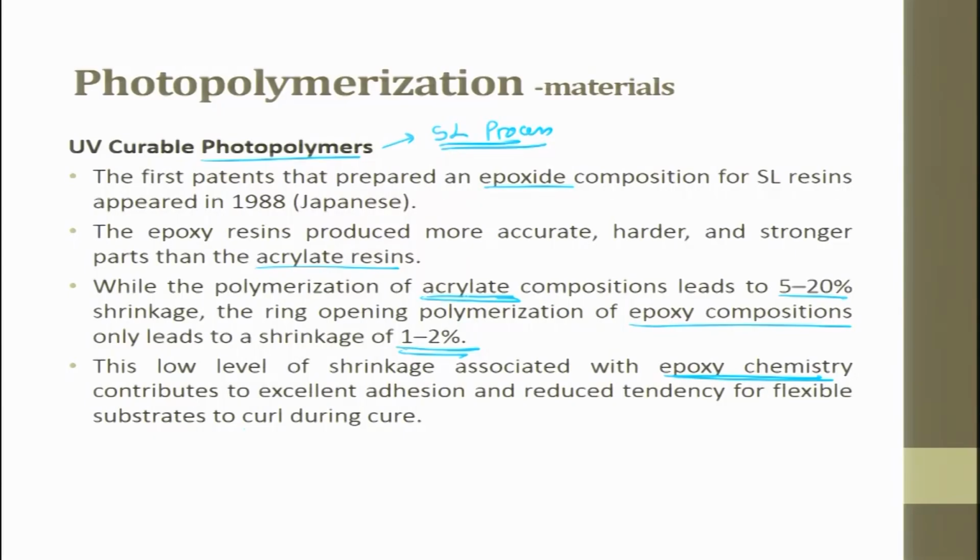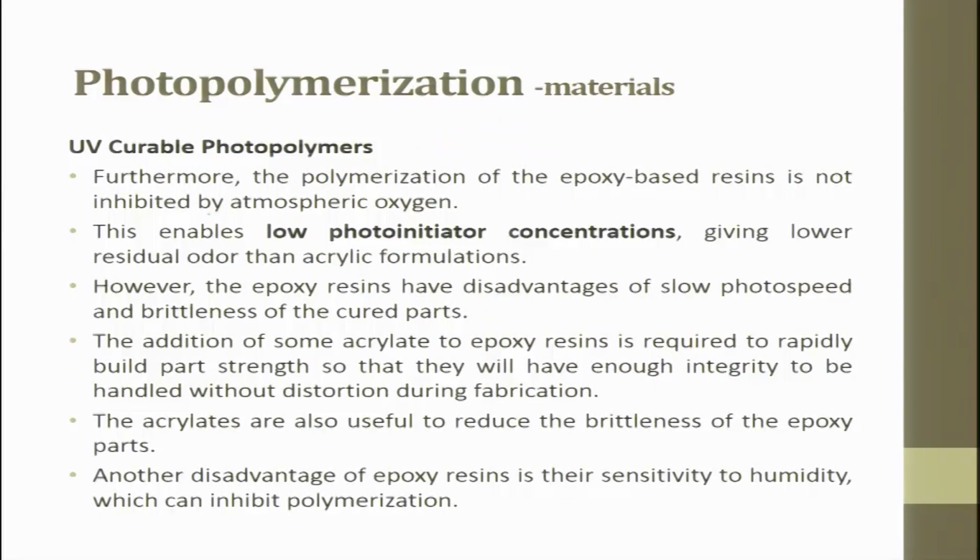So, from acrylate based we went to epoxy chemistry which contributes to excellent adhesion and reduced tendency for flexible substrate to curl during curing. Furthermore, the polymerization of the epoxy based resin is not inhibited by atmospheric oxygen. This enables low photoinitiator concentrations, giving lower residual odor than acrylic formulations.